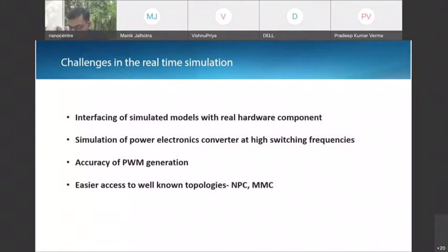This means that you have developed your power electronics converter in the physical world, and you want it to be integrated with software where your controller sits, a platform in which you can do the interfacing, where one part of your model is in the real world, whereas the other part is in the simulation world. This is the main reason why real-time simulators come into the picture.